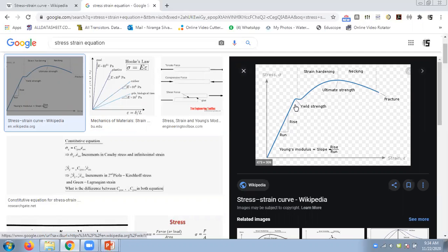So SolidWorks has nonlinear methods also. In the first few lectures, we will look at the linear methods only. So I assume my curves are always linear and follow Hooke's law. We calculate the strain, multiply it by the Young's modulus, and calculate the stresses.